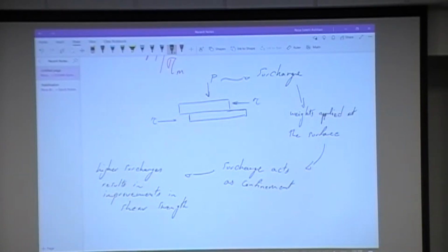And this is exactly that sigma that you see in the general form of the equation. You're increasing sigma, and you know that it's going to be ascending in nature, right? That Mohr-Coulomb failure envelope that we have. All right, so we have essentially two stages of loading. Stage one is application of the surcharge.